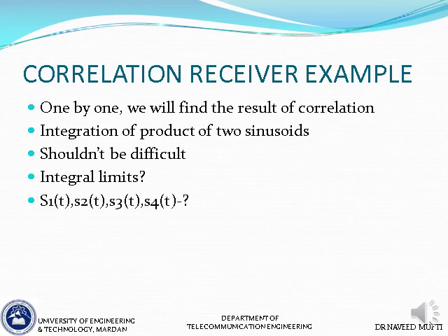And what are our four prototype waveforms? As you were told on the previous slide, the digital communication system uses 4 PSK with 4 possible phases: 0 degrees, 90 degrees, 180 degrees and 270 degrees.